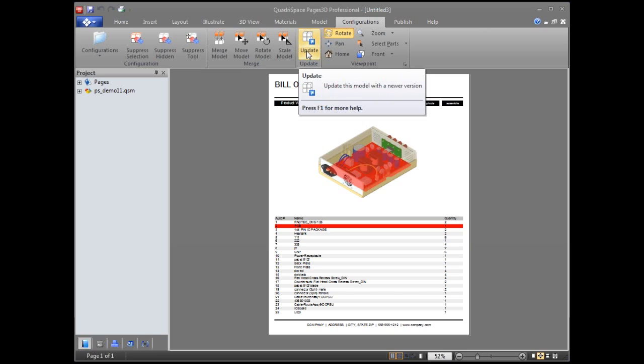It can have the same file name, but you re-import the 3D model, and all of your graphical content will be updated to match the new 3D content coming out of engineering. That means that your work, such as exploded views, won't be disrupted. You'll still have all the viewpoints and all the markups and everything that you've worked on as a documenter, but you'll have a revision of the document to be revision 2 or 3 or whatever. And we'll talk about it in a lot more depth.